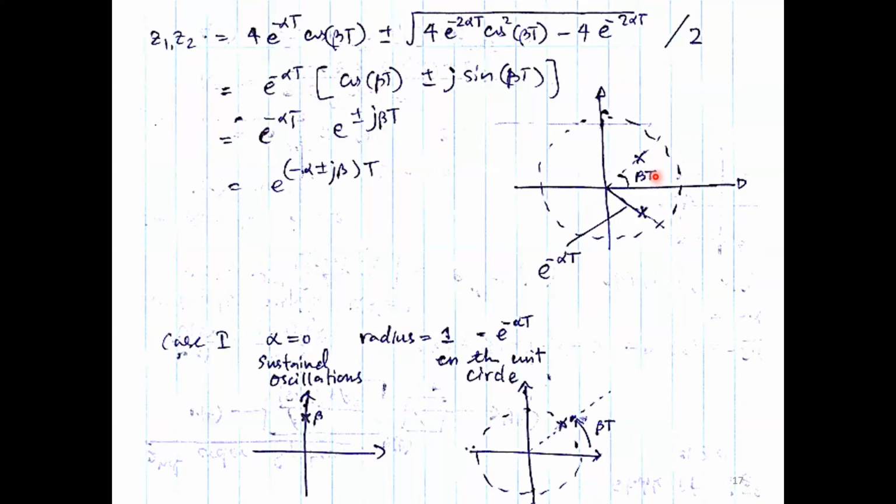If you further increase t, the frequency will further reduce and you are below the Nyquist rate. So there's nothing called below the Nyquist rate because the system is already generating aliasing frequencies. You can go down and down in frequency, and up and up in terms of t. When you increase t, you reduce your sampling frequency, and when the pole is over here, that is the Nyquist frequency.